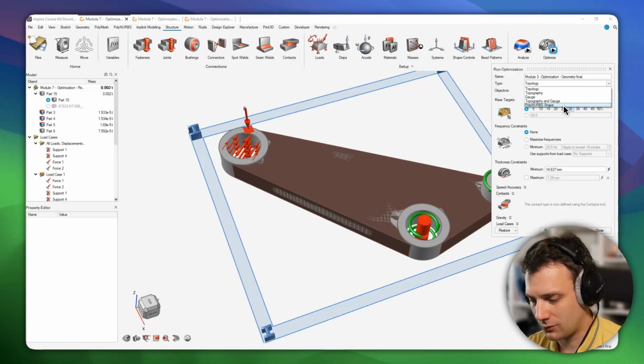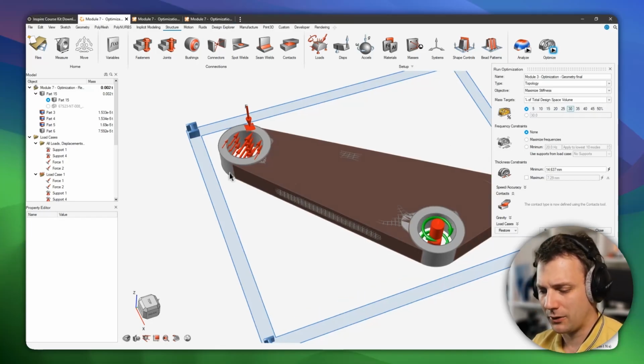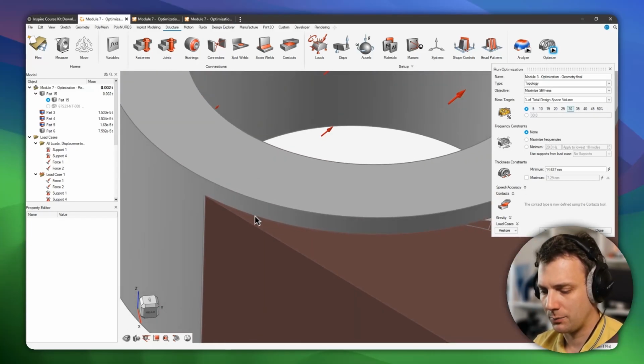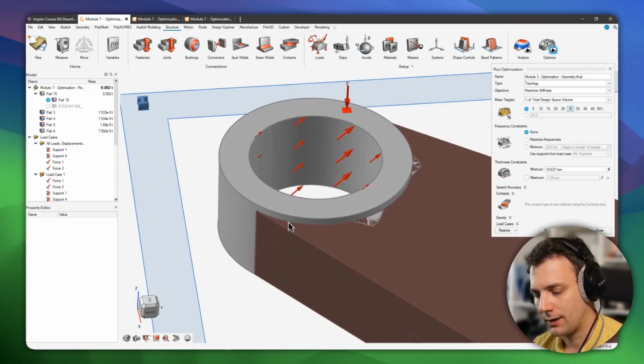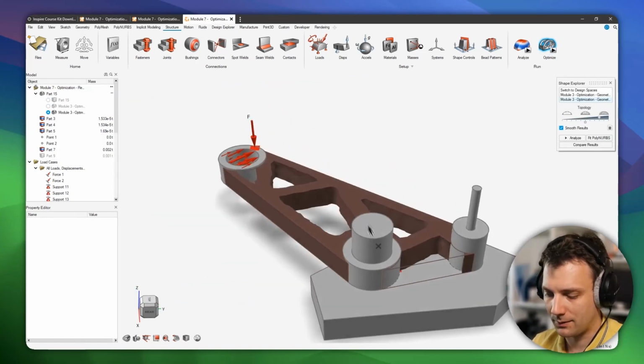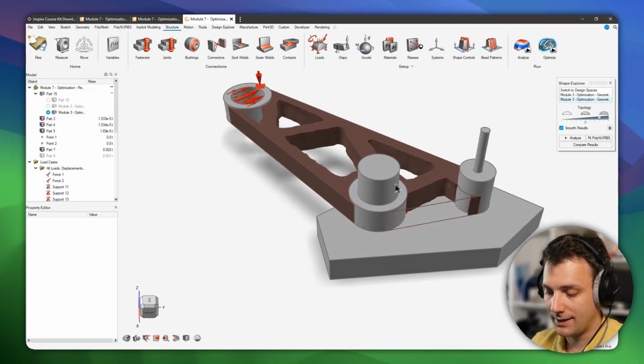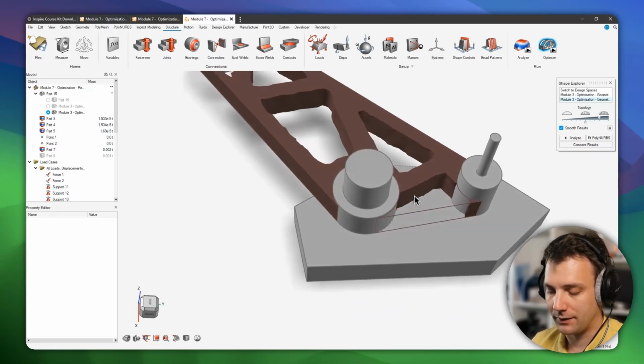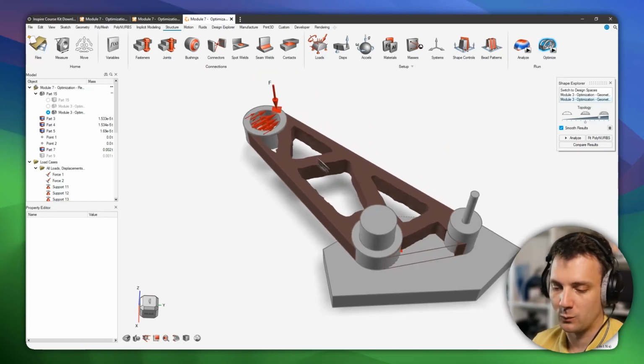So just summarizing, be careful with those little gaps, right? They could bite you. Be careful with the sharp edges, and also be careful with constraints that have infinite stiffness relative to each other. Be sure to double check that, if you have a stiffness between those two, the structure which comes out is not completely different.